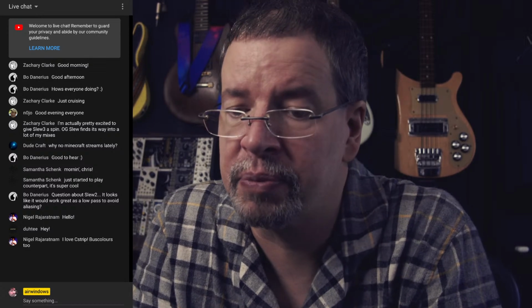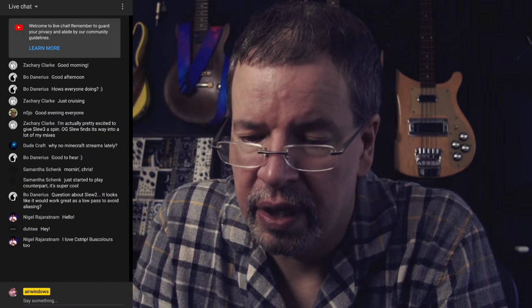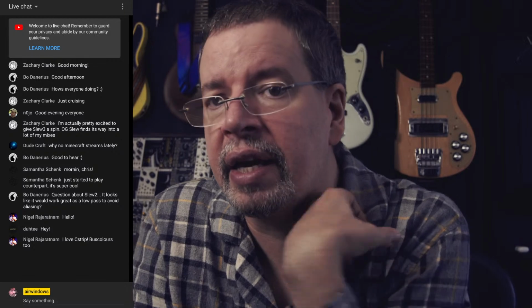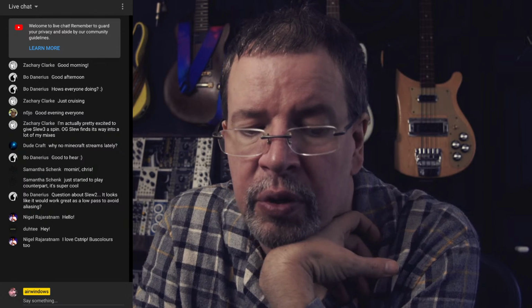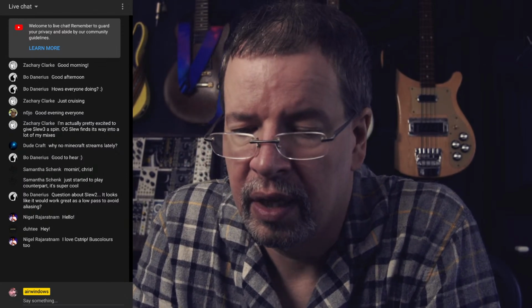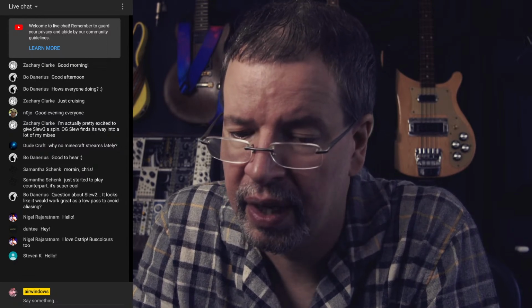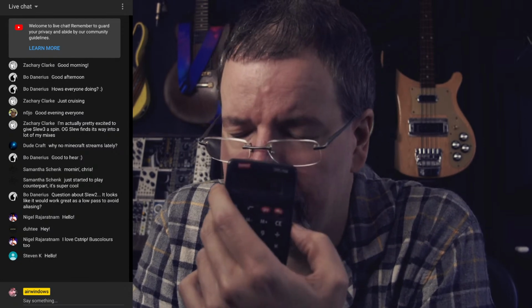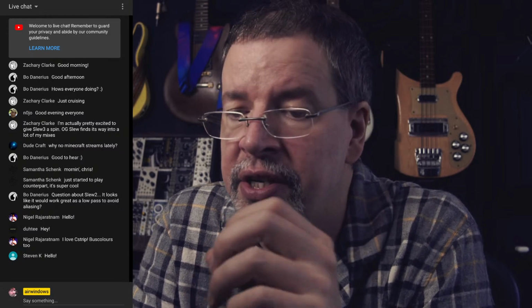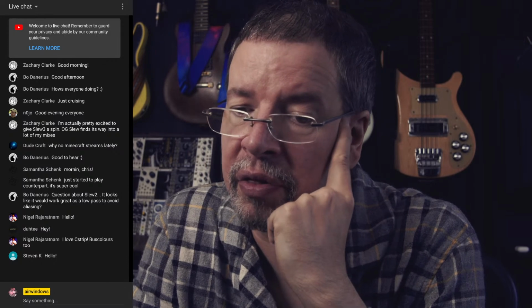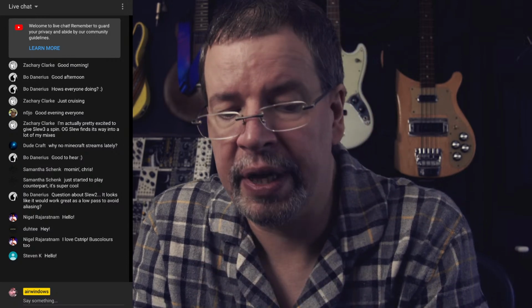And of course, another possibility is doing something like Focus does, which is you're wanting to generate an overtone and you're wanting absolutely no aliasing. So what you do is a brick wall filter and then just let all of the higher frequencies through untouched and cut off at 7.35K. And below that, be sure to generate just a single harmonic, a single third harmonic. And if you do that, it should be aliasing free.